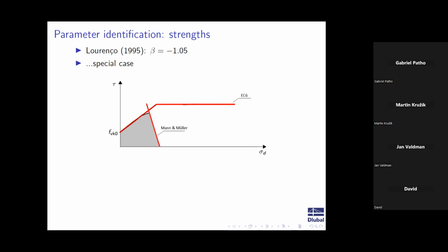We have some special cases. What about if the crushing happens much quicker? In this case, you do not get onto this plateau, but even before this shear stress, you have crushing of your masonry. In that case, we define our additional point exactly at the crossing. So my two yield surfaces should look like this.